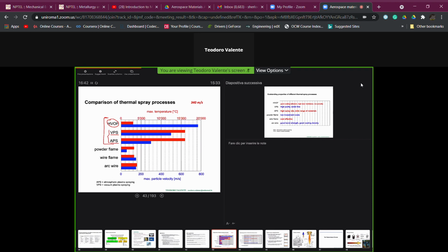And this cannot be neglected, because when we start with a metallic alloy of defined composition, and then we experience oxidation before coating fabrication during spraying, this means that the coating that we are going to fabricate does not have the same chemical composition as the starting powders, but it has another composition, it's another material. And so in that case, it's worthwhile to take into right consideration the possibility to use vacuum plasma spraying.